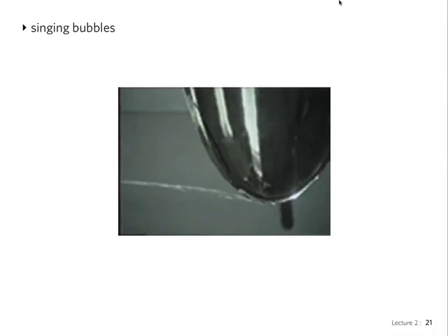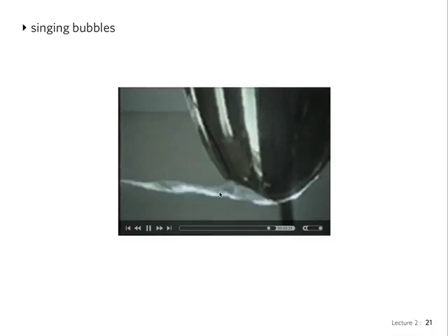First of all, here is another effect actually. That sound is generated by the bubbles. Cavitation is observed here by those bubbles. What happened in this movie is that water was flowing in this direction, and the velocity of the water is changing. And as it accelerates around this bend, the pressure drops below vapor pressure, the bubbles are formed, and the bubbles can produce that sound. So you can hear, and many engineers have a trained ear to hear when cavitation happens in some devices or pipes and so on.